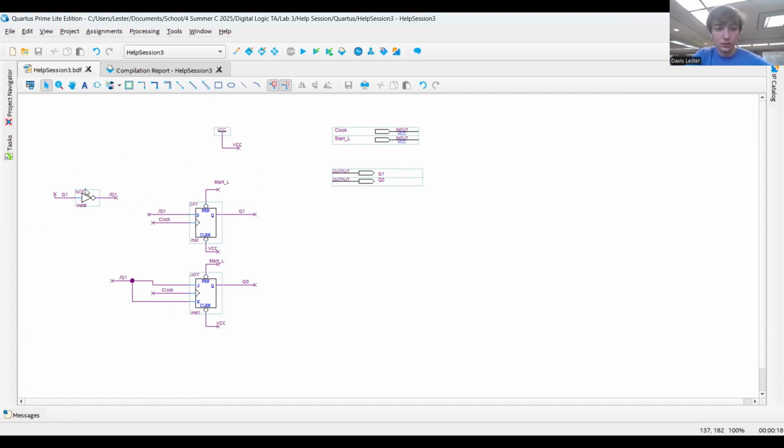Now, like I said before, I have logic going out of it from the current state into the next state, because our next state would be going into the flip-flop. But you alternatively could have logic going on this side, where you have logic from the next states into the current state, but you can't really do that, and it's frowned upon. So always have the outputs come out, go into logic, and then go back in, which we have here.